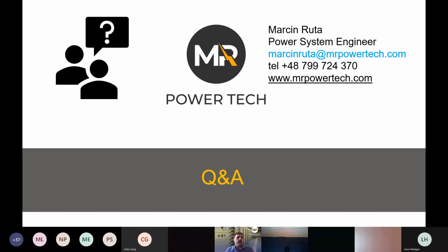And from the arc flash risk assessment, that's what we do. Arc flash calculation is not purely to tell people what kind of clothes, what kind of PPE they have to use. It is first to reduce the energy. And sometimes we do it so well that they don't have to use any specific arc flash clothes, keeping energy below 1.2 calories per square centimeter. So it's more about identifying the energy and then deciding what to do next.